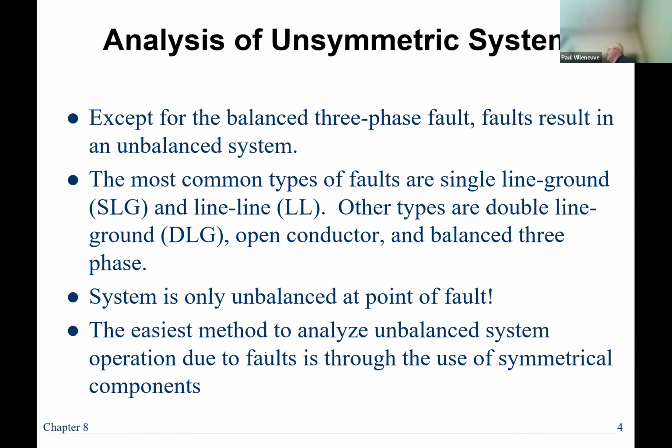We're not going to analyze that. It's essentially similar to a line-to-line fault is how you would do that. So we're going to focus on single line to ground, line to line, and double line to ground. And symmetrical components only works if the system is unbalanced at one point, which is where the fault is going to occur. All right? That's particularly important to us.